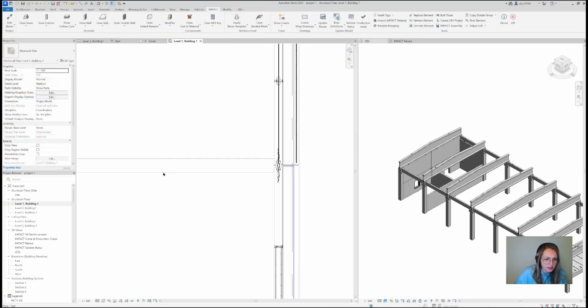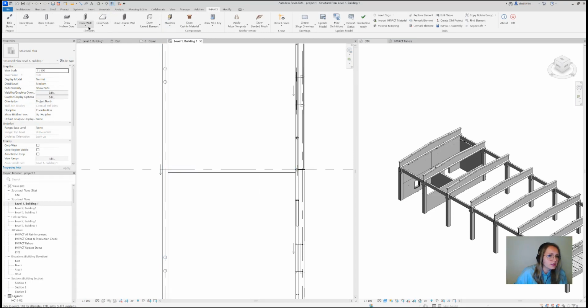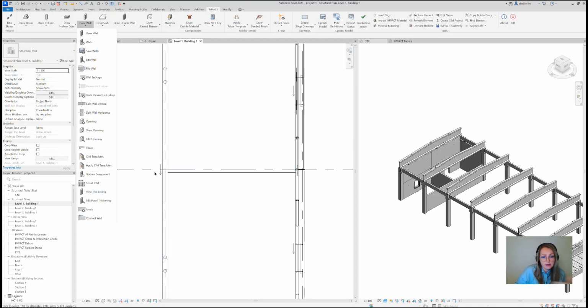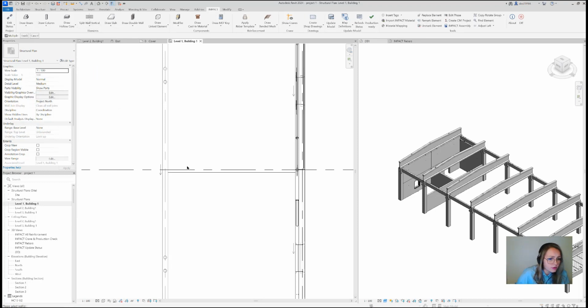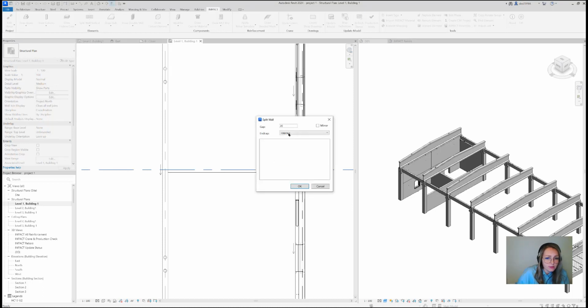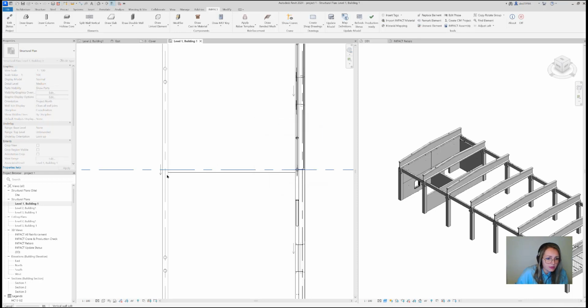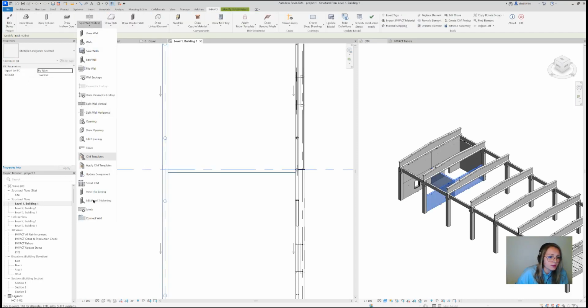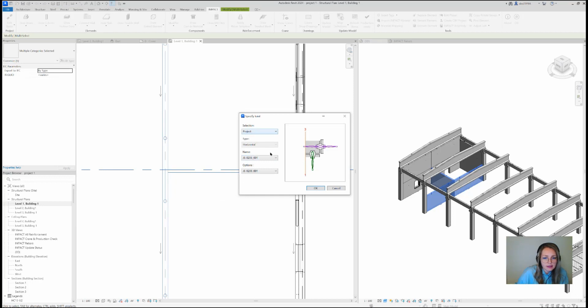And here I'm going to demonstrate again how easily you can do joints. The first thing you need to do is to split the walls. You can either draw two or split afterwards. I'm going to split this one vertically with the help of split wall command. No gap now because I'm gonna do the gap with the joint. So what I can do is select those walls and go to connect wall, and Impact is automatically scanning in my database. Do I have something for this 12, I would call 20 centimeters of walls? Yes, I have. I have this joint.